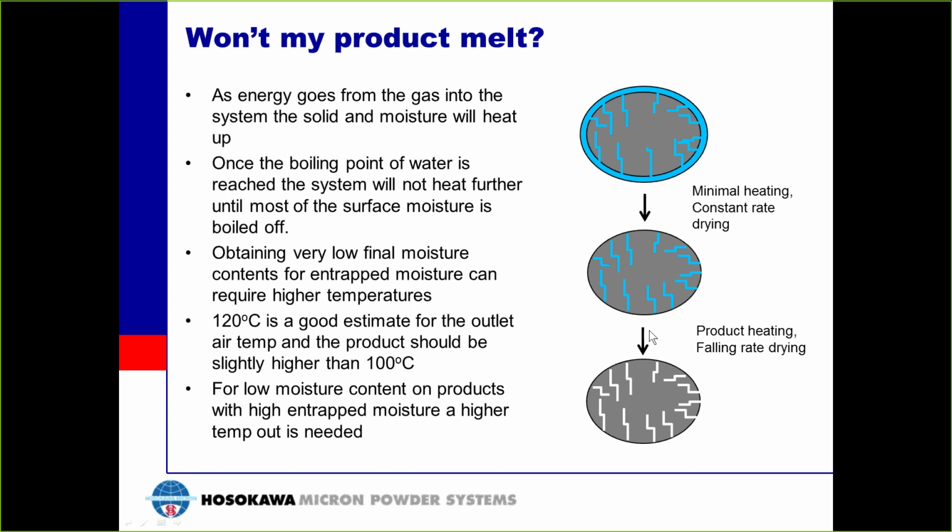But I want to make a few more good points on this slide. This is going to be minimal product heating, and it's also going to be your constant rate drying phase. Going on, as you continue to dry your product, you're going to see product heating, and you're also going to be entering your falling rate drying phase.